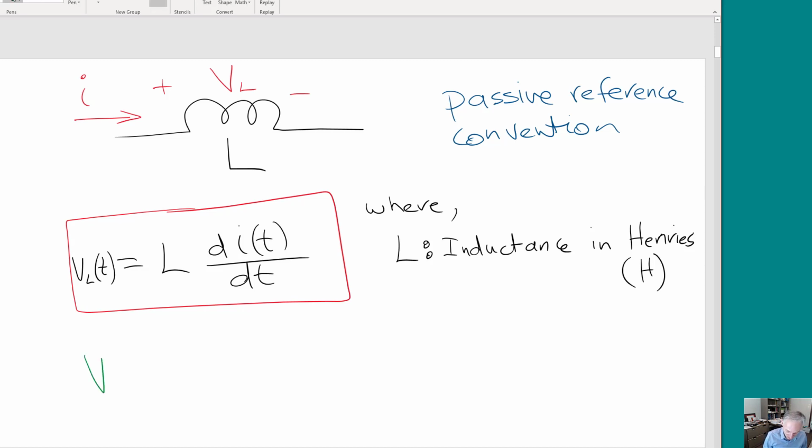This equation is also written V = L di/dt. And you can see some relationship to capacitors, right? I = C dV/dt. So this is the form for the inductors. Okay, and L, of course, is the parameter for inductance, and the units are in henries, so it's H, okay, like 5 henries or 100 millihenries as we saw in the previous example.